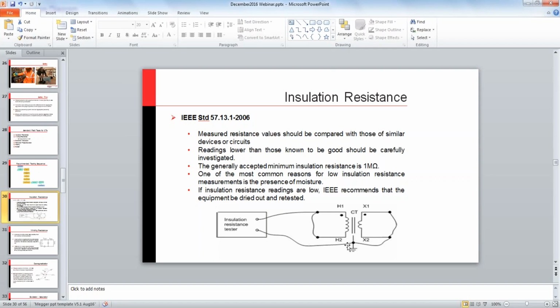So Mr. Dustin, I think there's no need for you to change any connection after you do it one time, which is connecting your primary side to the primary test leads, your secondary tabs to the secondary test leads, and then you're pretty much done with it. All the connection changes are done internally based on an MRCT that I know of.